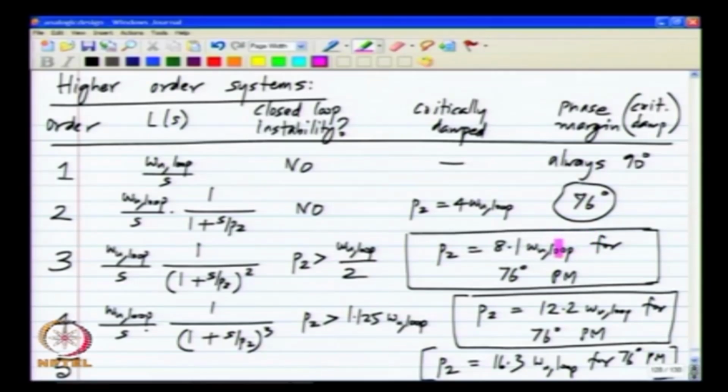So, 2 of them combined will add 1/4. Here 3 of them have to add 1/12, and 3 of them combined will be 1/4. Similarly, here 4 extra poles each has to add 1/16, and the combined effect will be 1/4. So, this also should confirm to you that each pole acts like a delay, and the delay contributes to ringing, and even more delay contributes to outright instability.